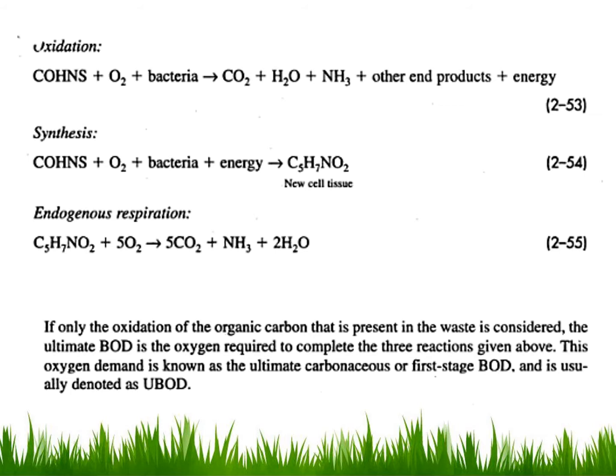This is our fundamental basic formula. It's actually not a formula but a symbolic formula representing the wastewater, because it is showing all the ingredients: carbon, oxygen, hydrogen, nitrogen, sulfur, and in the presence of oxygen and microorganisms, bacteria, they are producing CO2, H2O, ammonia, other end products along with energy.